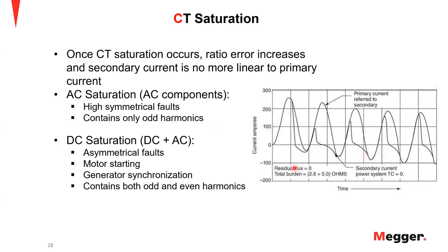If you look closely, we have the waveforms for the primary and secondary both here. Because of the CT saturation, we can clearly see that the secondary waveform is distorted as compared to the primary. And if you consider the RMS value on both sides, the relay is going to see a difference of currents and trip on differential. But again, we don't want it to trip on differential. So let's see how we can solve this problem.